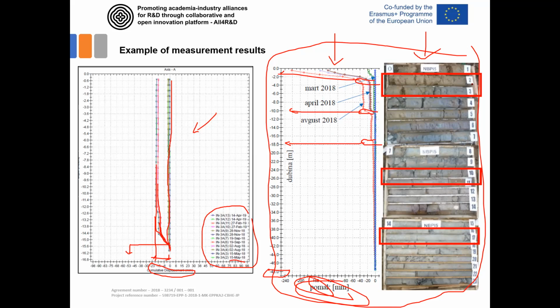This indicates some very complex sliding, where more than one sliding surface occurs. One is at the surface, the contact from the soil-like material to this fissured soft rock material, and additional sliding is also introduced here at 10 meters and here around 60 to 70 meters. You cannot find anything special at this location and depth, but obviously some sliding was recognized at this depth.